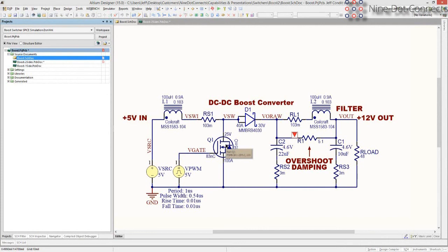How do vias on a two-sided design affect path impedance, resistance, inductance? Yes, again, you're always trading things off in design. You are going to be going through vias. I would not recommend smattering all the parts on 2 sides just because they fit conveniently. I would minimize your paths on 1 side. In this case, there were only two parts pushed to the back side, and those were specifically there to try to minimize current paths. So it was an optimization to go to two sides. I would recommend, if you can do your design on one side really cleanly, that it would be beneficial to do so. And you could have a ground plane under it to help shield everything.